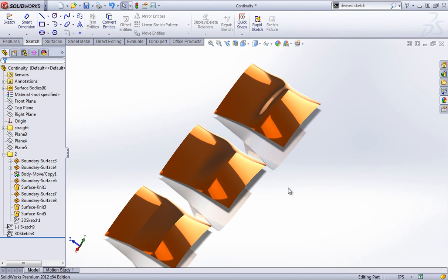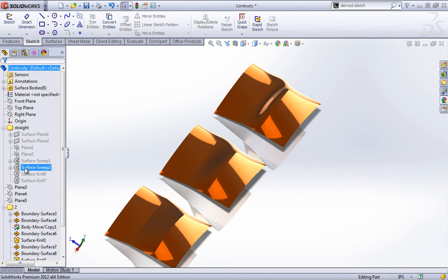So the main takeaways for working with curvature continuity are to generally try to just produce the best looking surface possible. Typically C2 continuity is going to be good enough, and then you can use things like the face curves to make tweaks to the model as well. And in straight transitions, like I showed earlier, generally a tangent continuous surface will look fairly attractive.